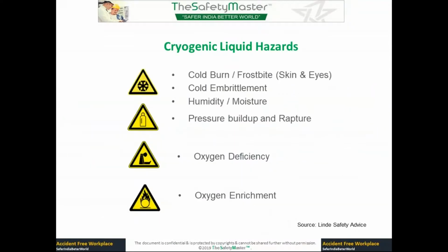Cryogenic liquid hazards are basically that they are cold. This is a symbol you will find whenever you deal with cryogenic liquids, on Dewars or cryogenic cylinders. You will also find this symbol on the cryogenic cylinder because of pressure build up and rupture.